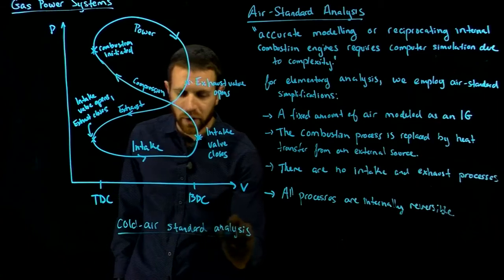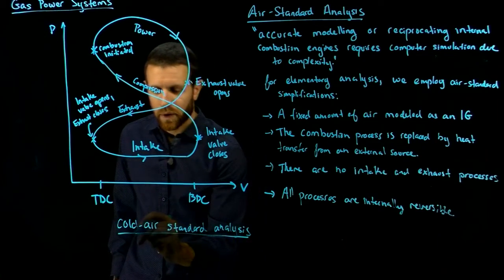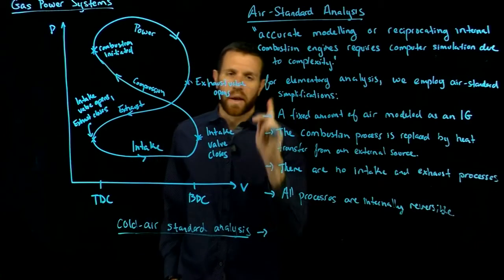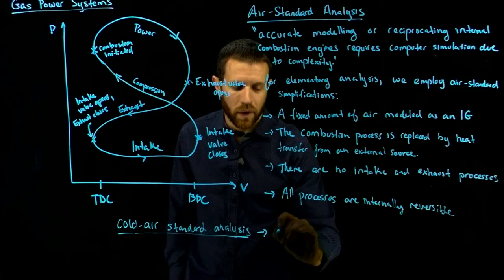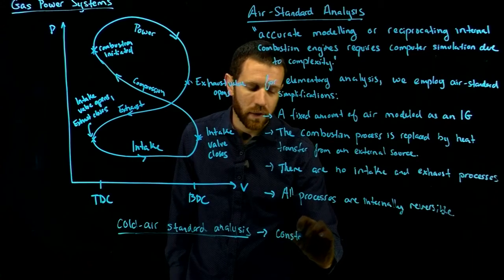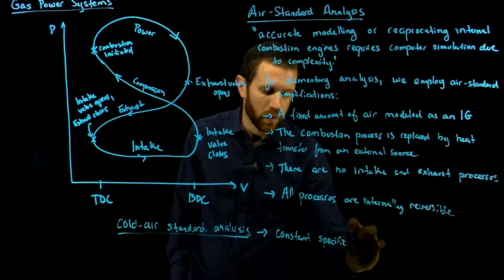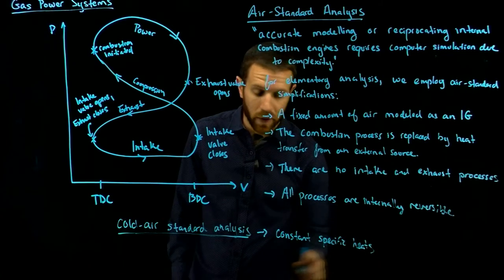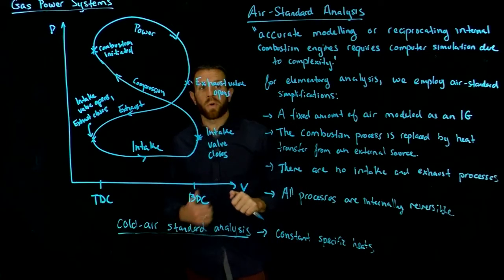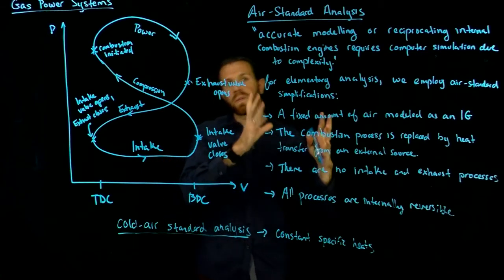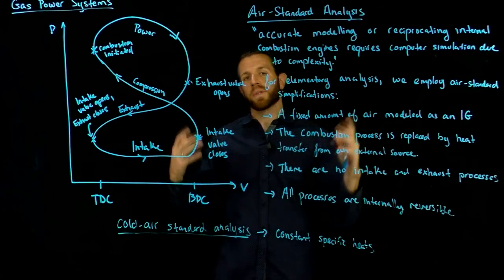And a cold air standard analysis takes all the assumptions of an air standard analysis and adds one more, the assumption of constant specific heats. So in subsequent videos, we're going to see numerous examples of air standard cycles and use these assumptions to help us generate simple models for them.